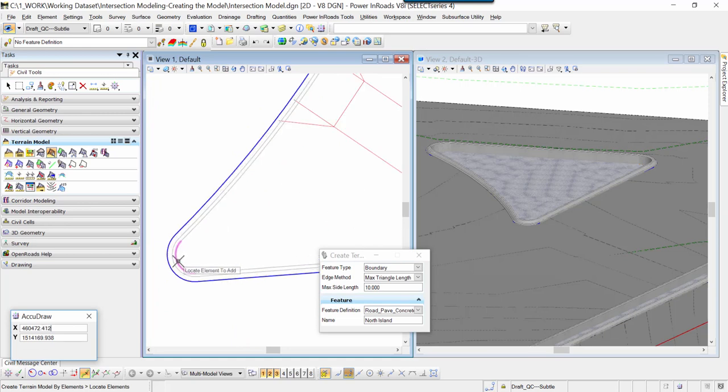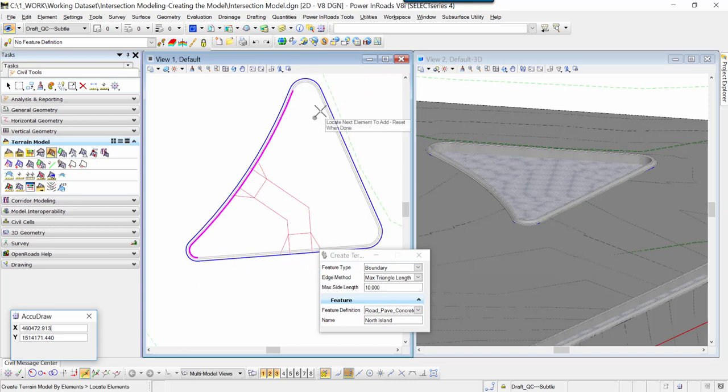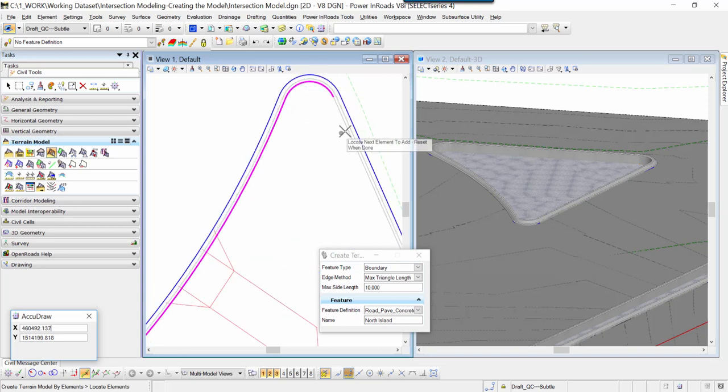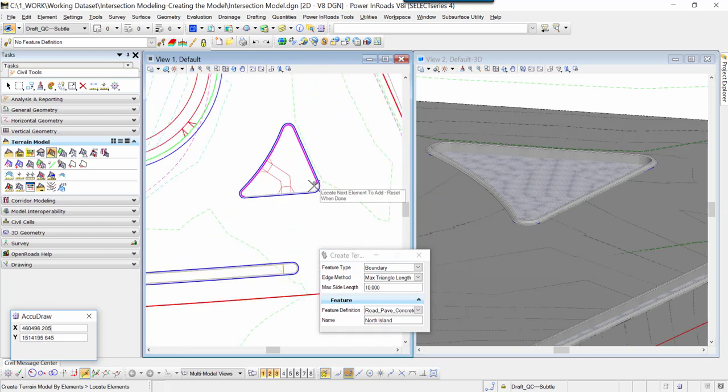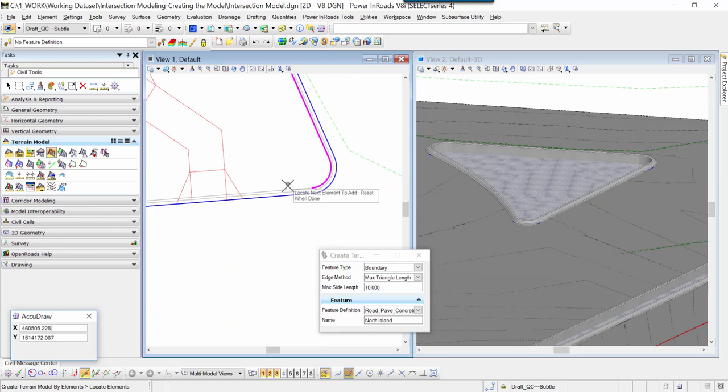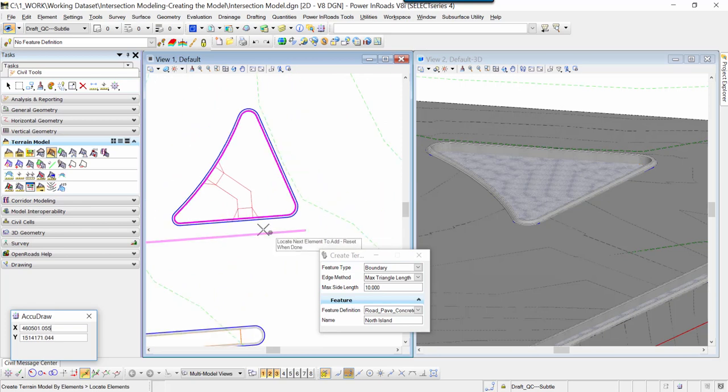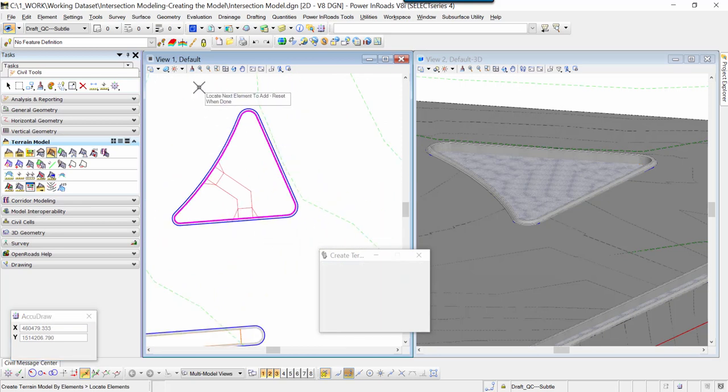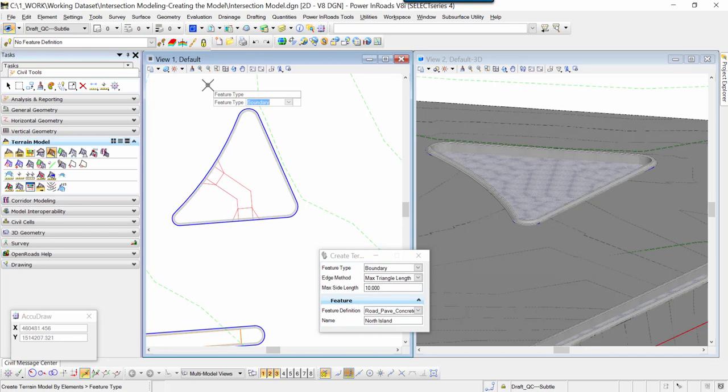As you're selecting the elements, it's best to zoom in. Be certain before you actually click on the element, as you hover over it, notice that the element is called Curb Back Top. You just want to be careful and select the back of the curb elements around the interior of the island. And once you have those selected, you right click, move to the next step.